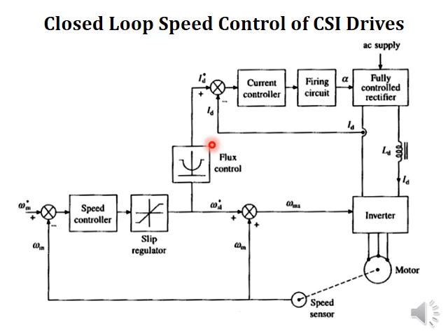only the frequency will be varied. Same as the case of a voltage source inverter. So we know that below base speed operation is known as constant torque operation because flux is maintained constant, and for above base speed operation, since flux is also varying, it is not a constant torque operation but constant power operation is achieved for above base speed operation.